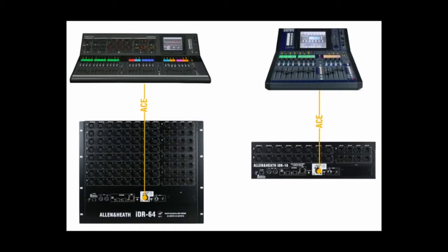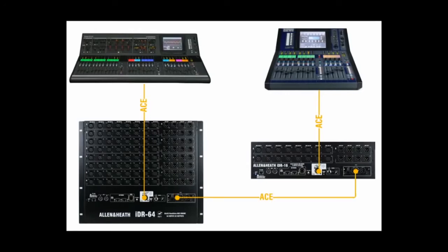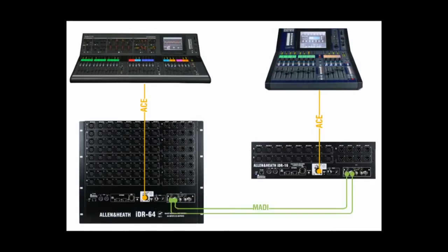The same type of network option card must be fitted in port B of both mix racks. For simple point-to-point, our proprietary ACE protocol is the most cost-effective option. Other cards are available to integrate with third-party devices or build complex daisy-chained and star topology networks. Refer to the card fitting instructions for details on connections, settings, cabling and more.